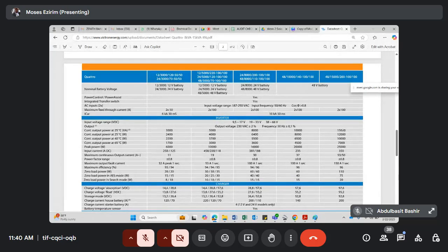Now, in terms of watts, you just have to multiply with the power factor to get this. When you realize that where you want to put your inverter, the temperature there will be around 40 degrees Celsius, don't size using this capacity. Data sheet is very, very important. Don't size using this capacity.